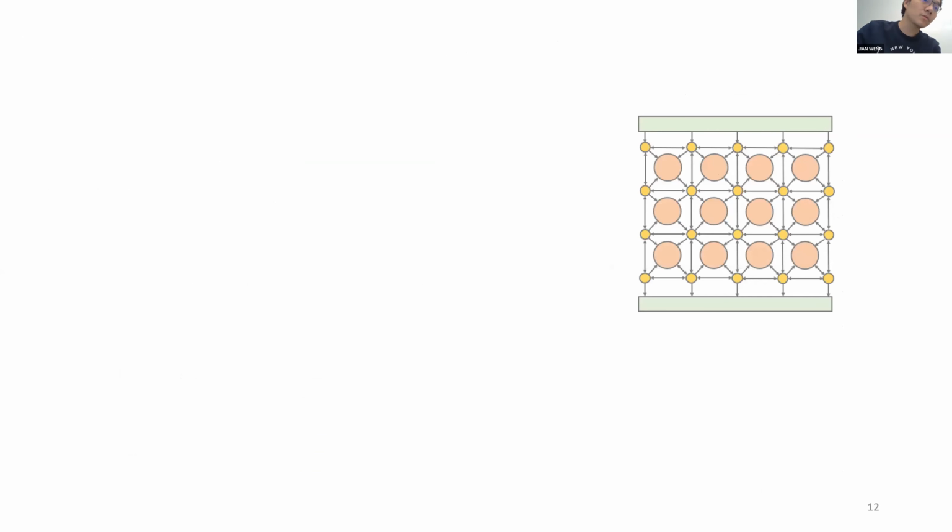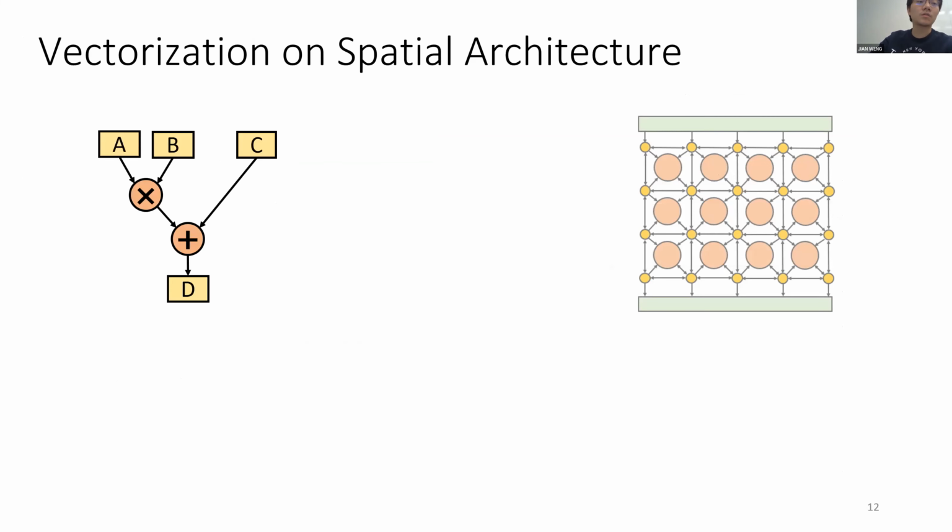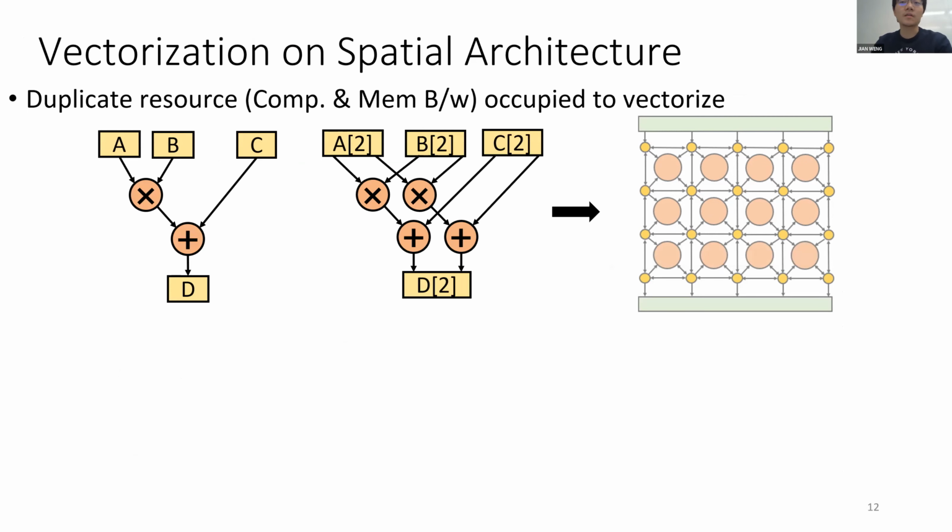And here we come to the computation. As I mentioned before, the graph execution makes the interdependent instructions fully pipelined. And what if we're greedy? We want something similar to vectorization. We just duplicate the instructions and increase the bandwidth of the coordination FIFO. You may say, oh, there's nothing special about the vectorization here.